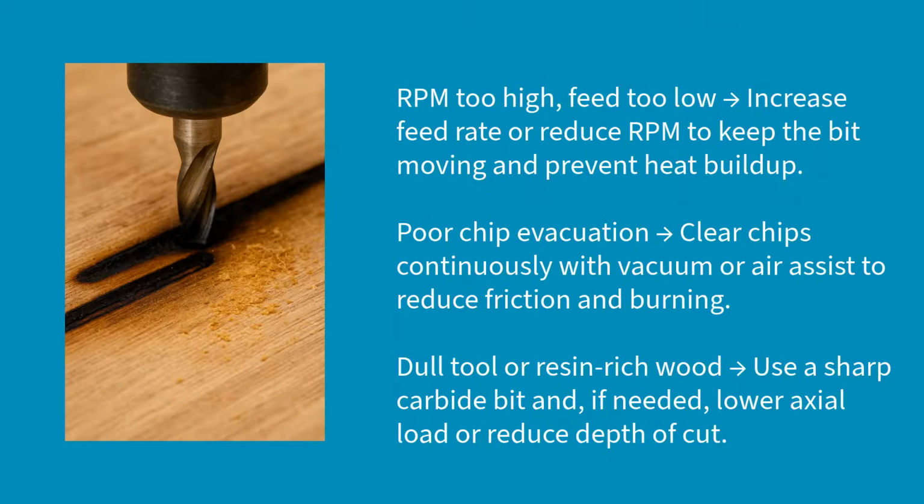Next, and something we talked about a little bit, but we're going to get a little bit deeper into, is if you see burning on your tool path. If you're seeing burning, there's a couple of causes for that. One is that your RPM to feed rate, RPM is too high and your feed rate is too low. Try increasing the feed rate while reducing the RPMs to keep the bit moving, but also prevent heat buildup.